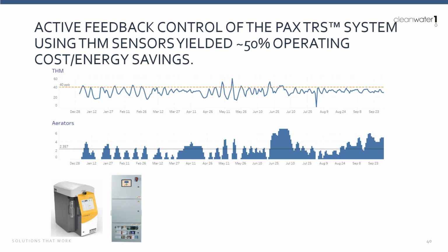They liked it. Got a very sophisticated water quality team at San Jose Water. And so they did some work to basically understand, well, what's an acceptable level of trihalomethane leaving the plant? They said, all right, well, we're actually quite comfortable leaving the plant if we stay less than 40 ppb. So here you can see the results of our effort. On the top graph, we've got THM concentration on the vertical axis, time on the horizontal axis. You can see our 40 parts per billion treatment goal.